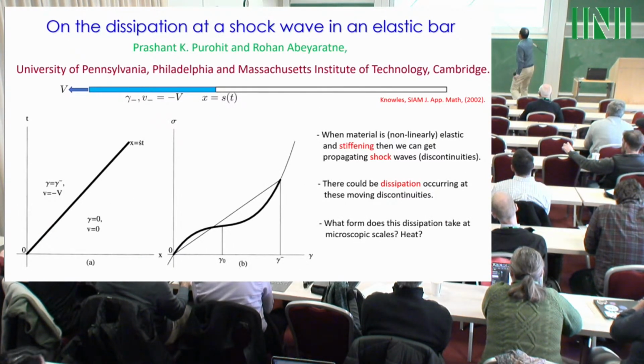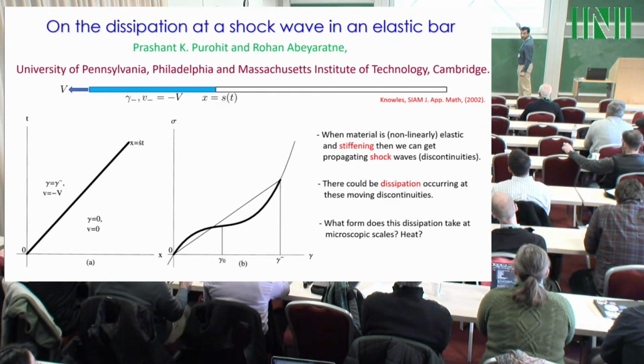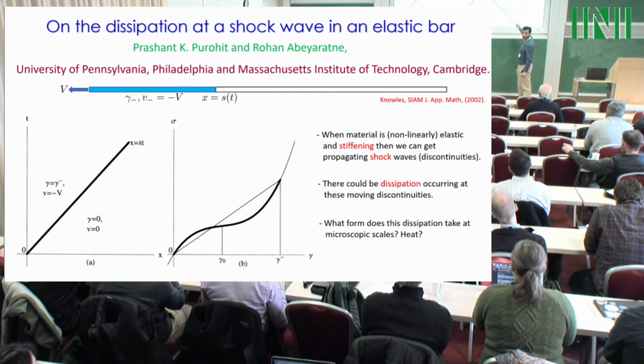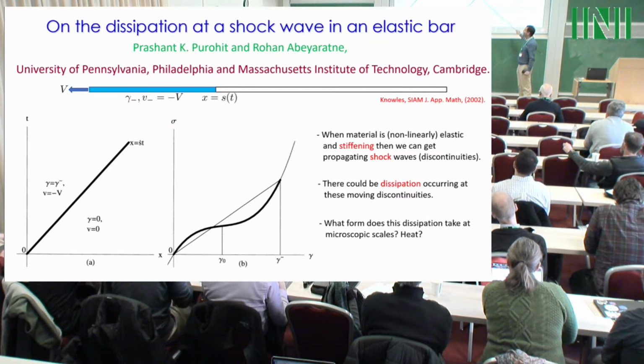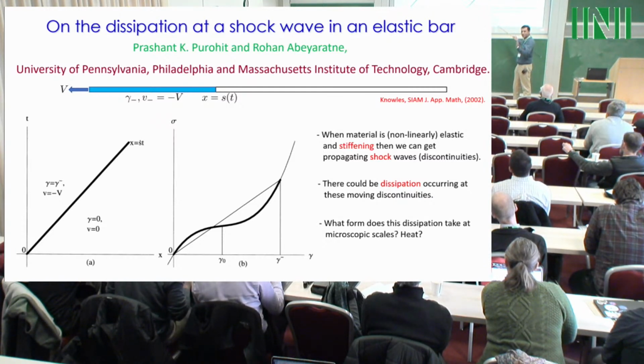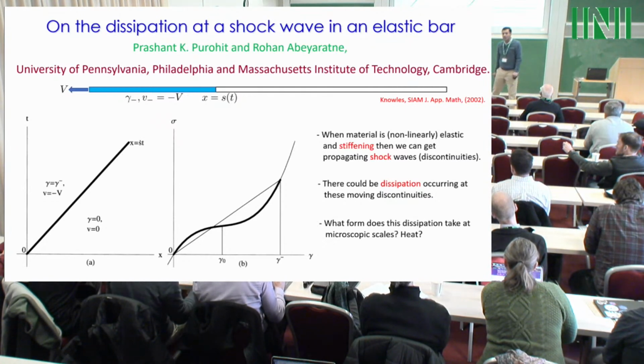So that was a theoretical problem. But this branch of the stress-strain curve for rubber is a stiffening stress-strain curve, so one can think of such a material as the one that we have in mind, not with the rest of the curve, where there is first softening and then stiffening, with strong dissipation in this material, which would need to be accounted for. Okay.